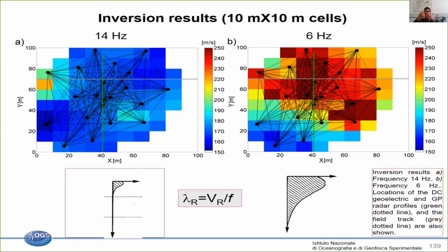And what you are doing when you correlate and stack, you try to remove all these signals which are randomly coming, and in this way you can enhance the one that is always propagating between the two sensors. Maybe this is very weak and at the beginning is masked by all the other signals, but with time and stacking, it's the only one persistent. And that's what you are trying to get out of this. It's just a simple way to explain it,